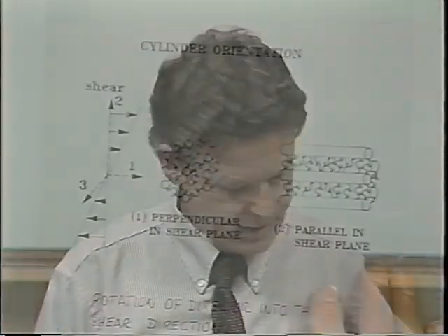to maintain intermediate structures. Due to the high molecular weight of the middle block of the polybutadiene, the global rearrangement of that structure is fairly slow. The rearrangement within the cylindrical domains will be fast because the styrenes are very low molecular weight, but the matrix is of high molecular weight, and we have time to quench any intermediate structure. Actually, we found that we could leave those structures for hours to reorganize the pattern. The rotation of those hexagon patterns might need hours at this temperature. Very, very slow process. So the experiment is like this.